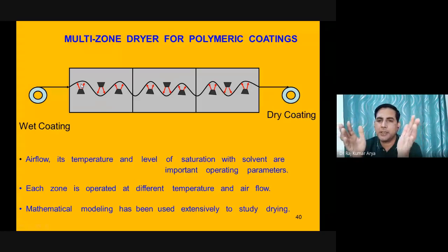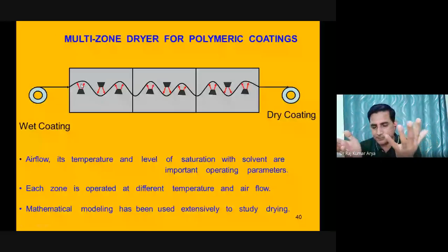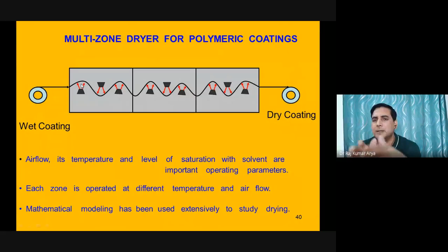In the dryer, you are maintaining drying conditions. So you now have two choices. One, just like home painting, we don't do anything, so everything dries at the same airflow and the same temperature. But at industrial scale, we have the option to dry the entire length of the dryer at different conditions. Let's say primarily you have a very high amount of solvent. So you can dry at a very high temperature and very high airflow rate, because nothing would happen in that case.